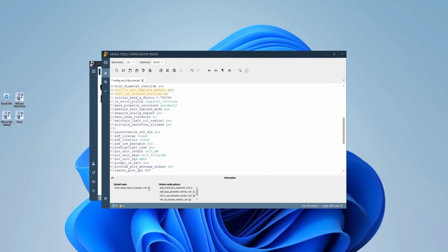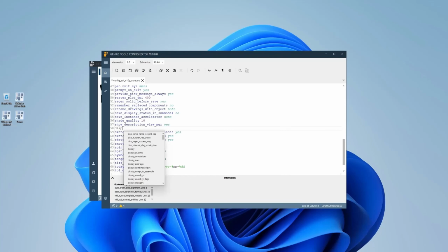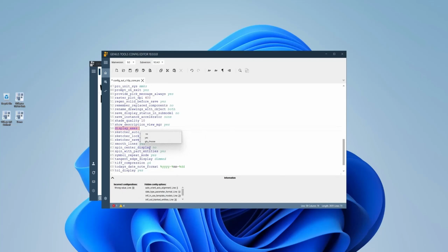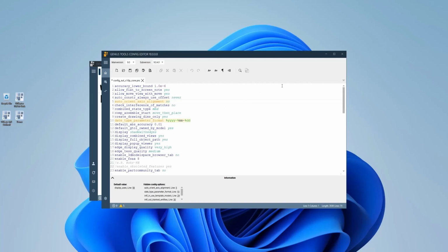So you could open up the editor in this application, and this will then show the user all the available text options. You don't need to go into Creo to find all the options. It will show you if you've got any hidden options or any invalid options or any duplicates or default options. In this example, if I type something and don't put in a value, you'll see in the bottom left hand corner it shows you that the user hasn't specified the value. If you then type that in, it will come up and say, okay, this is a valid option now, but there's still a warning sign, it's highlighted in yellow.